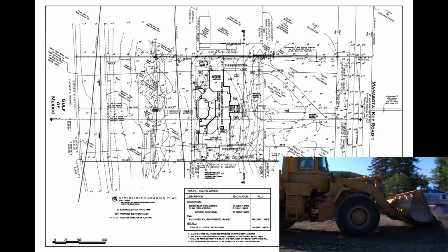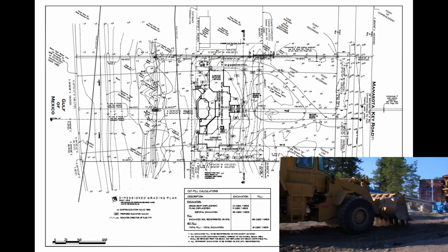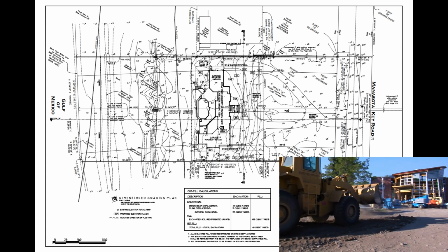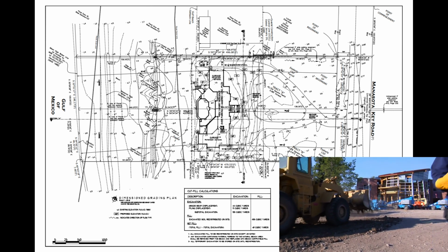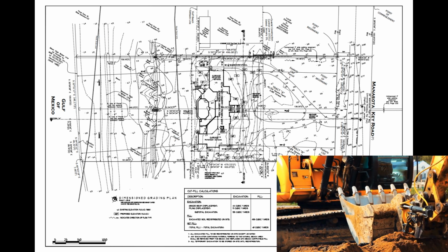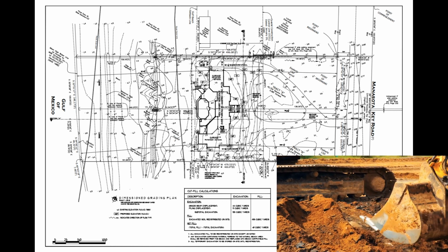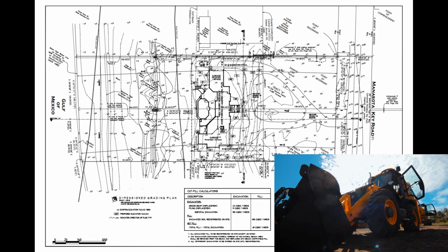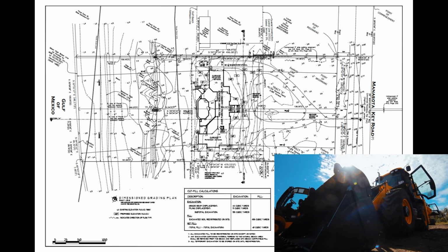This is a collection of elevation markers which will allow rain runoff to flow in a planned way. Other information shown on site plans or grading plans may be trees, utilities, drainage pipes, lot boundary markers, adjacent or nearby roads, and a north compass orientation symbol.